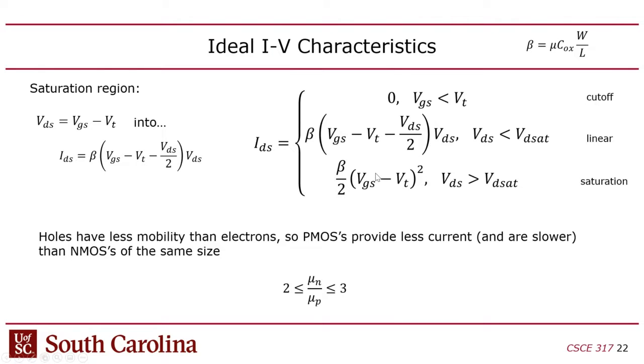Now, obviously, if you want to build an amplifier with a giant transistor with a larger width in order to drive more load, that would also affect your beta. The way that beta is typically represented, it includes both the charge mobility, which is linked to whatever transistor you're building, as well as the width-length ratio. And you never want to make the length larger than the minimum. But the width is something that you can manipulate as someone doing layout.